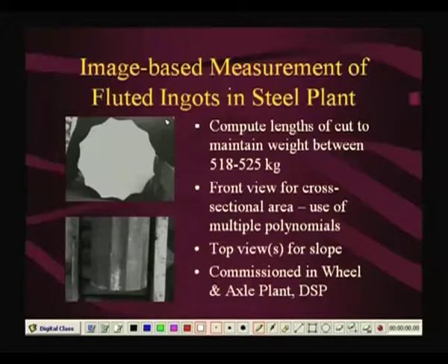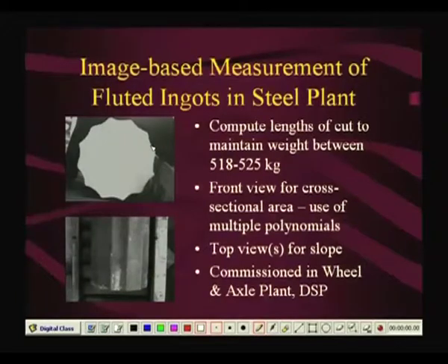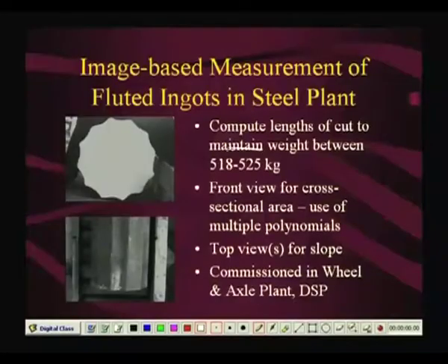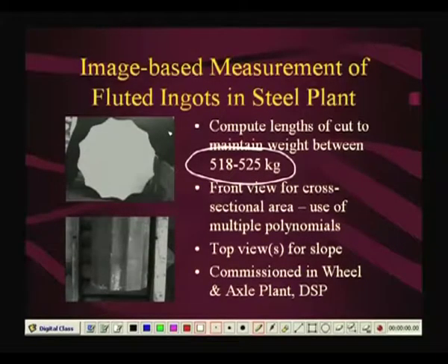Now, the railway wheels are made out of these ingots in the Durgapur steel plant of SAIL. The ingot is long, so they generally cut it into three pieces, and they were required to cut it into the right weight, because railways has a requirement that its wheels must be of between this to this weight, which is a fairly stringent accuracy. In 500 kgs you need to have an accuracy of plus minus 3.5 kgs, which is not so simple to